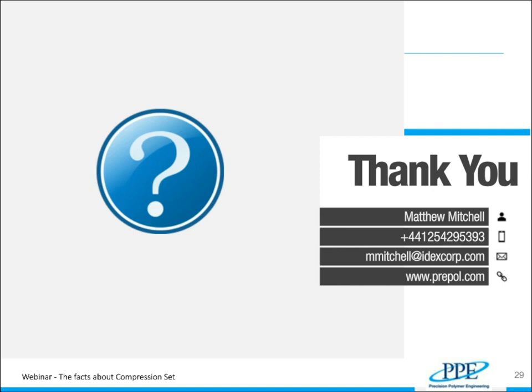It's very relevant as, say, a first pass. What I often say around compression set is, take FKM for example. The vast majority of FKM materials are tested at 200 degrees C for 24 hours or 22 hours. And then the numbers are available for people to review, and for a first pass you can compare, making sure you're comparing apples with apples as opposed to apples with oranges.